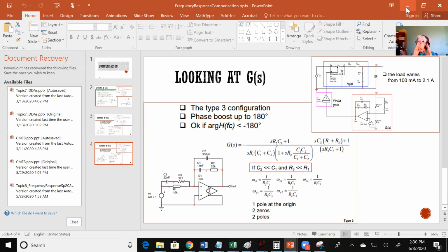If you have a very small phase margin, then you get ringing. I tried to use that instead of having a separate clock or a separate oscillator circuit. I tried just to get the thing to ring like mad for a little time and then damp out. So if you want it to oscillate for a certain amount of time, that works.